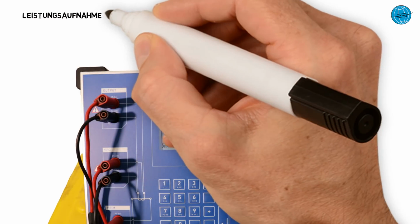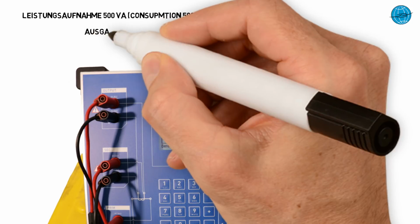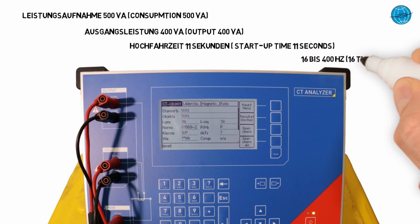The power consumption of the CTA is 500 VA, the maximum output power is 400 VA effective, and the startup time of the system after switching on was about 11 seconds in our test. The application range is between 16 and 400 Hz.